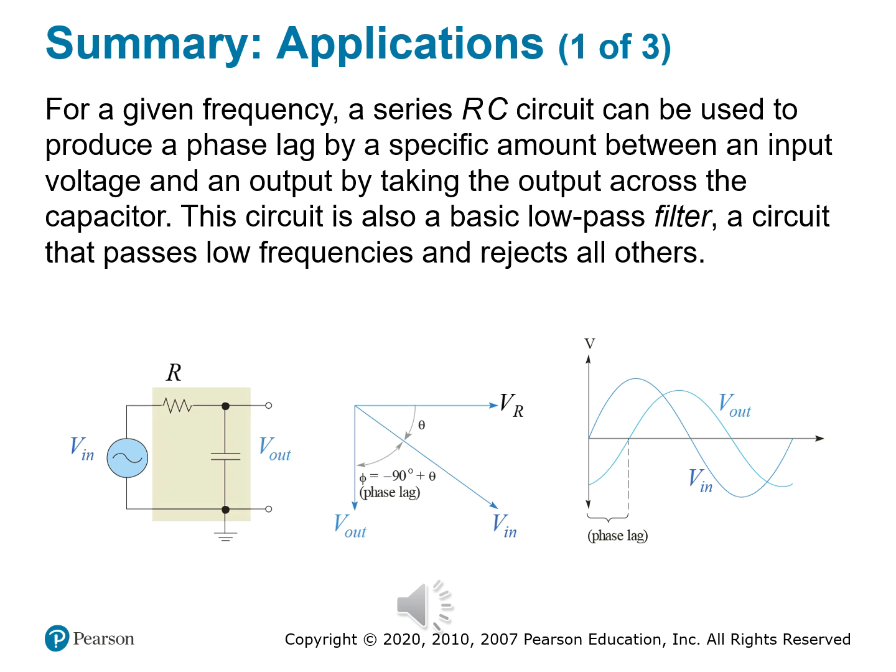And the amount of lag depends on the phase angle theta, which we covered earlier with our trusty impedance triangle. And the result is a phase lag circuit. And we express it as phi is equal to negative 90 degrees plus theta. This gives us a finely tuned control knob for phase manipulation. You might see it the other way, where phi is equal to theta minus 90 degrees. I like that form better.